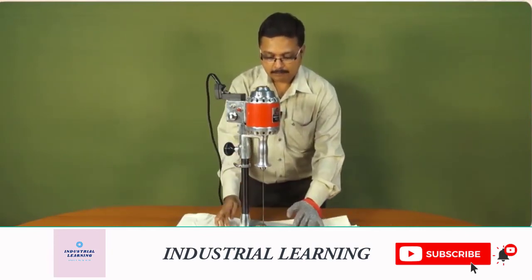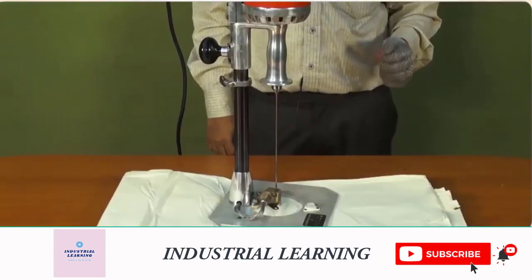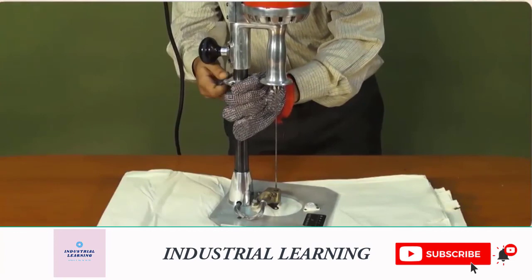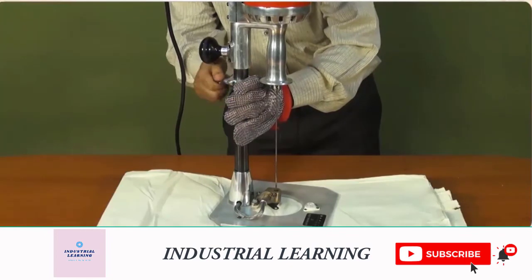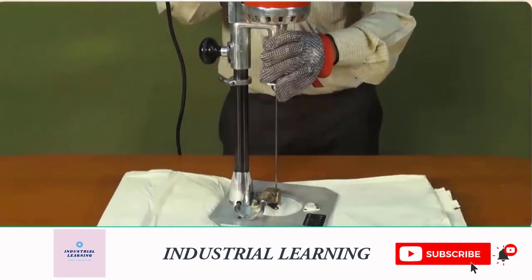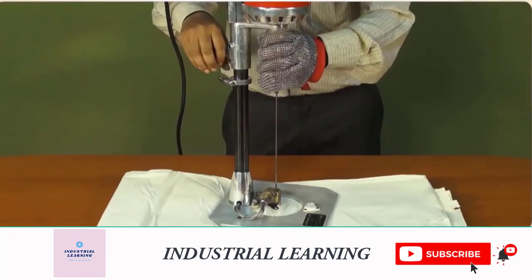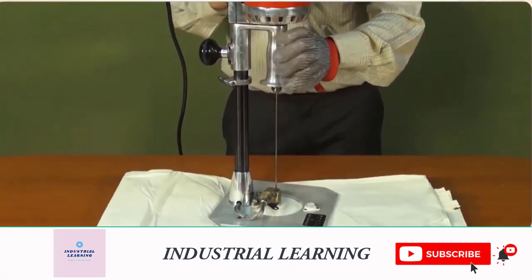This machine also has a base plate and has a leveler. The depth of the needle is changed by loosening this screw and either bringing it down or bringing it upwards, and once you tighten the screw the depth is set. While doing the hole, you switch on the machine, wait for a few seconds for the machine to get heated, then plunge the needle and take it up. Now the hole is made.